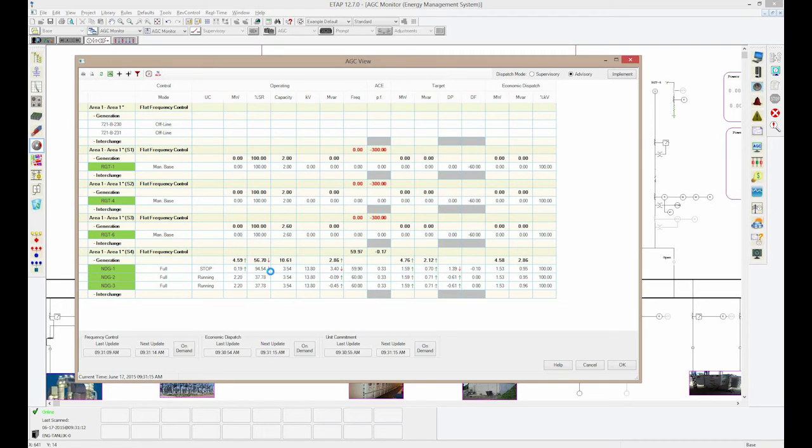And the spinning reserve is a combination of actual spinning reserve detected by the metering devices in the system, as well as the forecasted values from the renewable sources. So in order for me to determine the spinning reserve, I have to look ahead, include that capability in along with the current load in the system, and then decide, do I have enough spinning reserve in the system to keep operating the system safely or not?